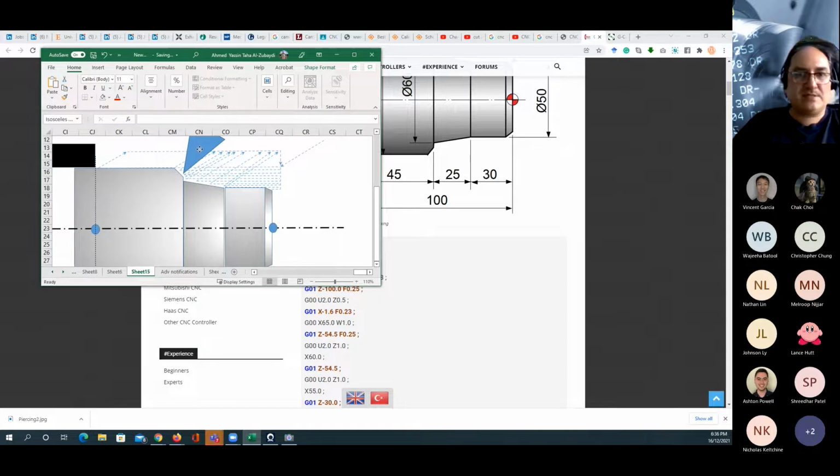And we set the feed rate once again. Now you can see that the feed rate is going to be different if we're going to move along the X-axis or along the Z-axis. This will be a different value. Usually it's going to be higher than the one we're using for the face milling.